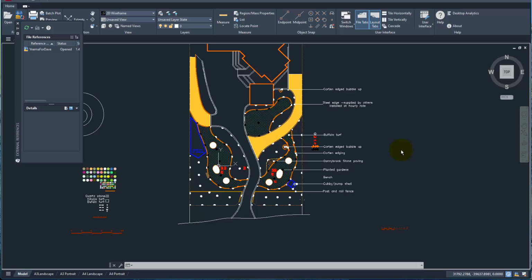Well, here's the final result. I've just used the ODA tool to convert the DXF file that was output from gCADPlus into a DWG, and it looks and feels and behaves like a normal DWG file in the AutoCAD environment. After all, this viewer is just a crippled version of AutoCAD, so we're very happy that we can now send this drawing off to the client.